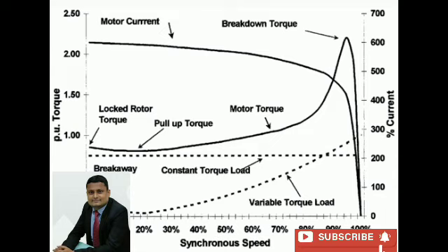So now calculate the volume of all the teeth in the stator. So VTS equals ATP' into hs into Sg. So weight of all teeth in the stator, WTS, equals VTS into rho iron. So rho iron, that is 7860 kg per meter cube.